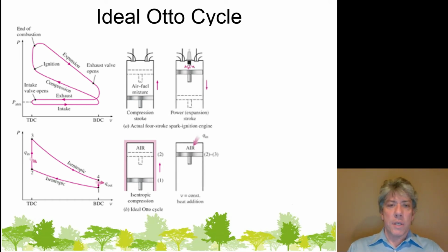The next process that occurs in the real engine is the compressed gases are lit up, right? It's got fuel, the spark plug goes off, that starts the burn, and really what happens is that burn takes some time. You don't want all of the air and fuel to ignite at the same time. If that happens, it's almost like a sledgehammer hitting the top of the piston. It's an impact type force instead of a smooth power stroke where the fuel has a little bit of time to burn. It's not good for a real engine.